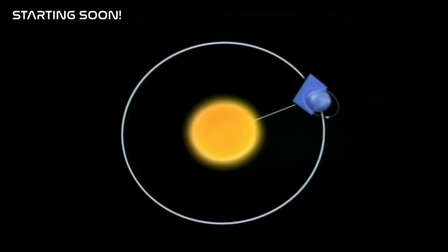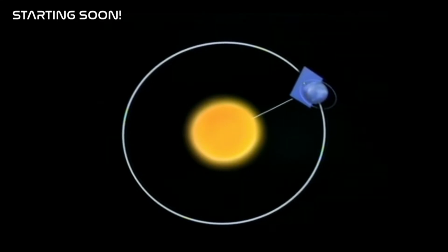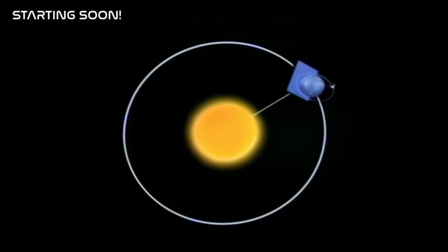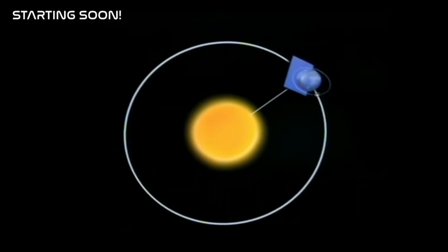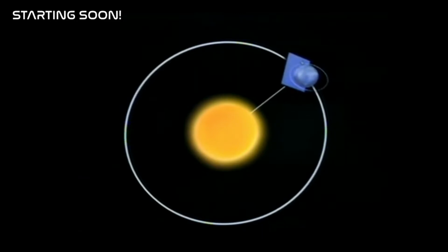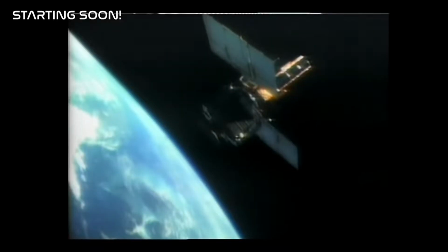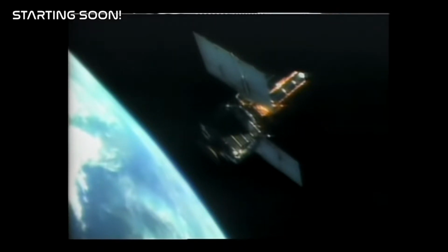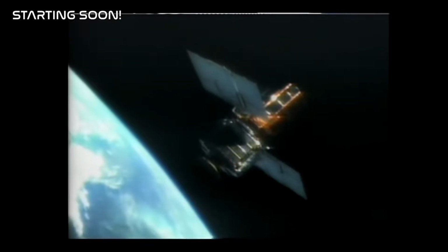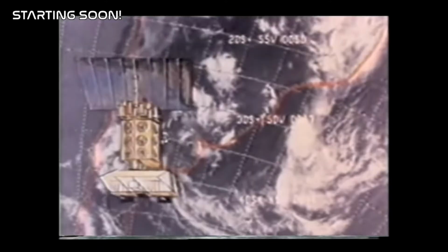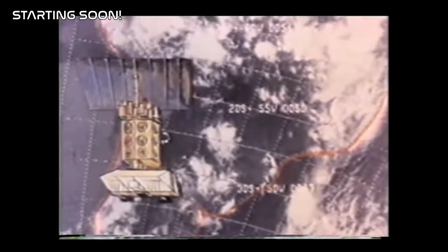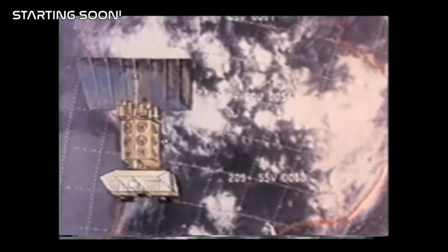If the satellite's period is then synchronized with the rotation of the Earth, it will pass over the same point on the Earth's surface at the same local time at a regular interval. A sun-synchronous satellite ensures that a constant sun angle and uniform lighting exist for the same field of view from pass to pass. Satellites such as those in the Defense Meteorological Satellite Program and Landsat are sun-synchronous, imaging the entire Earth on a regular schedule.